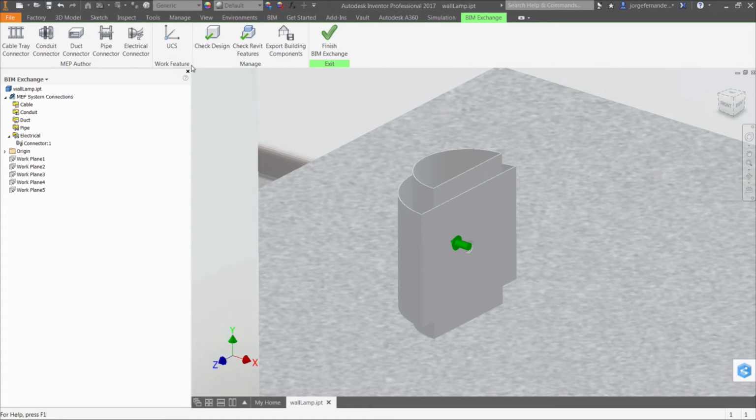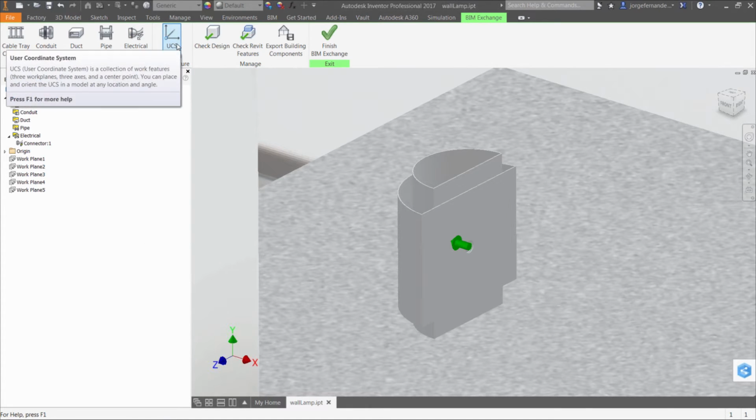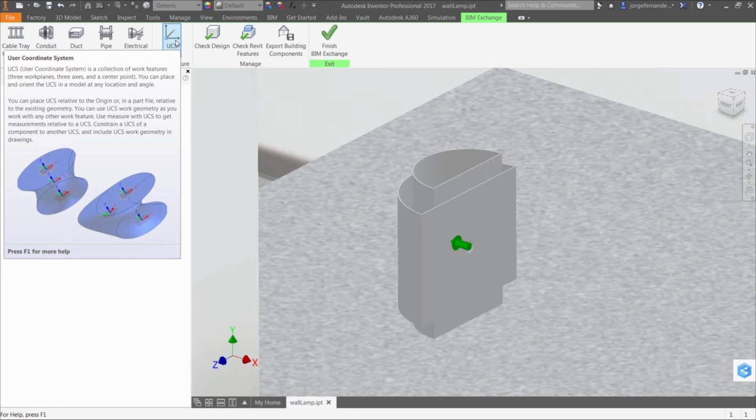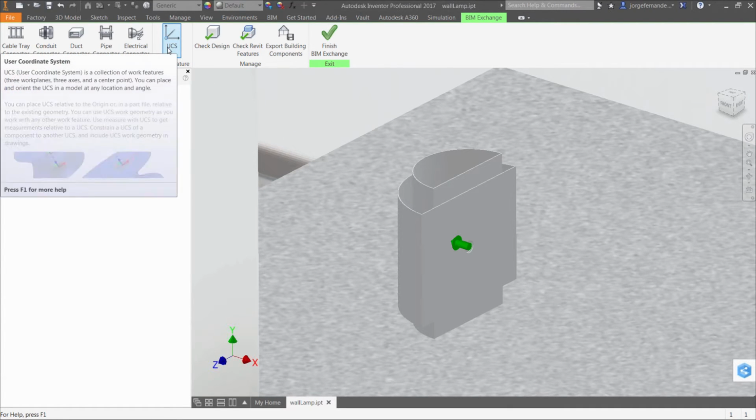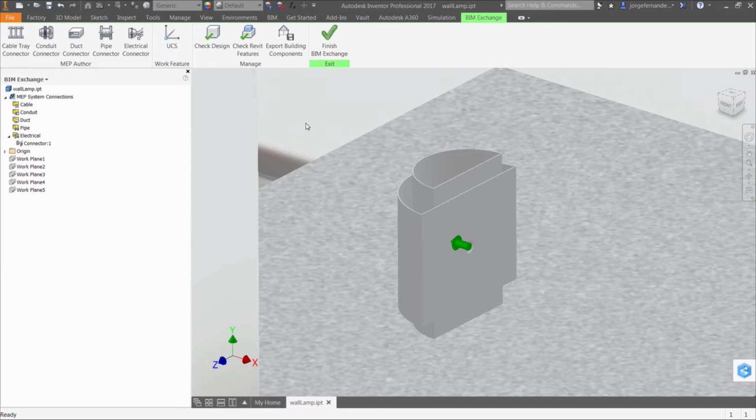The other thing I bring up, this is kind of important. I want to make sure I stress this part, because whether you're creating the file or asking for this file, in manufacturing we tend to look at the z-axis as our front view, whereas in architectural and civil we look at the z-axis as up and down, where we put the plan down. I'm sorry, I thought I had the camera on, but we actually look at the plan view on the table, and that's the z-axis. So that is two differences between the two industries, and it is a very important thing, that feature that we have here available to us, to be able to tell it how we want the UCS to look.